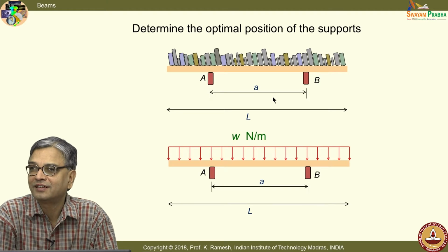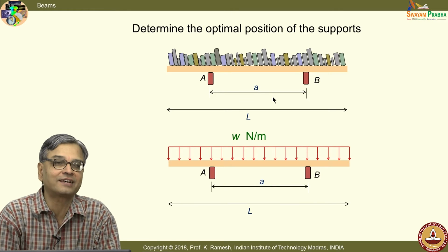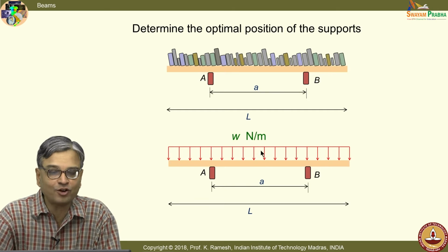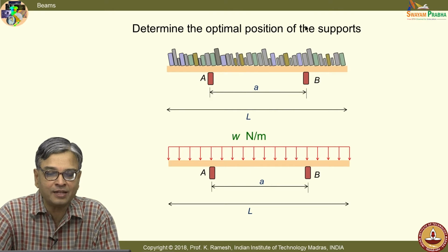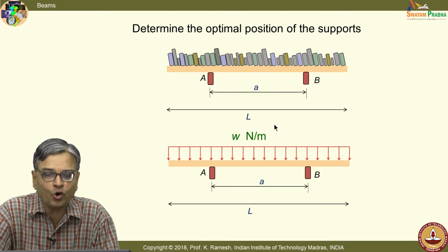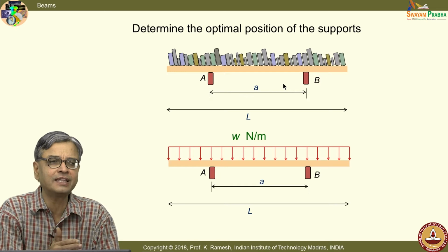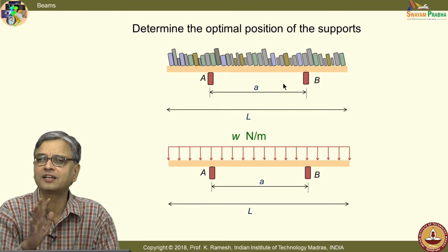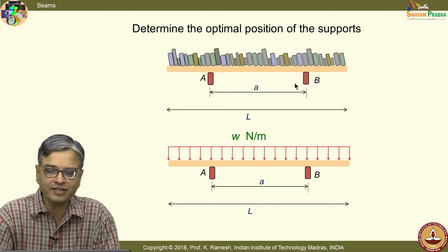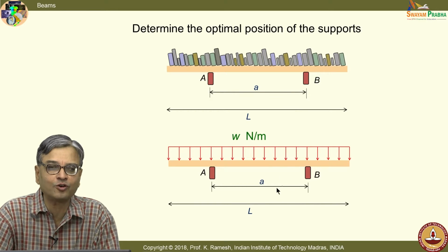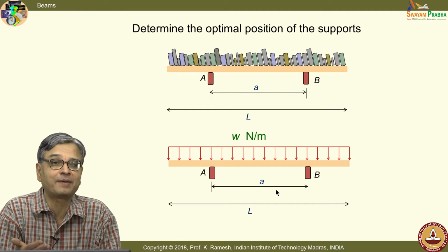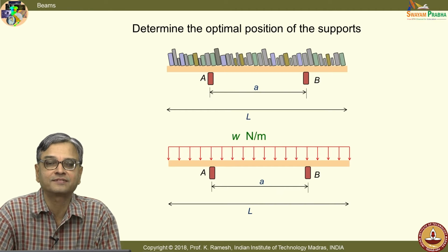L by 2. Now, let us go and look at the mathematics and find out whether our intuition is correct. For the idealized loading, the moment I idealize the problem, I do not worry about the actual problem. The answers will closely match with reality with a small amount of error, which is tolerable for a given design situation. Intuitively, you feel that A should be equal to 0.5 L. We will see what way the mathematics is going to give us the answers.